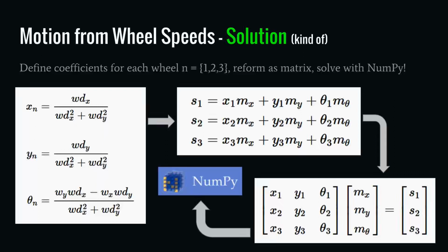and we can then express that as a matrix containing all of those things. And then you realize it's late at night and you can't actually be bothered to remember how to do this properly, and you throw the entire bunch into a numerical solver. There's a reason for that, though, that is better than simply laziness, which is that we have 3 wheels, 3 unknowns, therefore there is a unique solution that says, given this combination of wheel speeds, what our motion is.